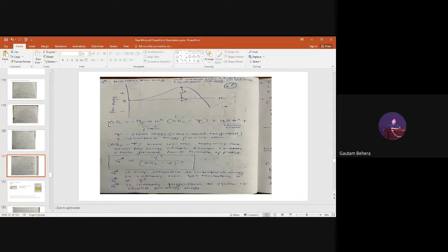How many of you can say, when a precipitate will form from a matrix, what should be the condition? If this is the overall free energy change during this transformation, this term should be negative or positive? Negative. Very good. Delta G should be negative if a transformation is to be possible. But now this is r cube and this is r square. Do you remember this one? R is the radius of the particle, and this is a free energy.